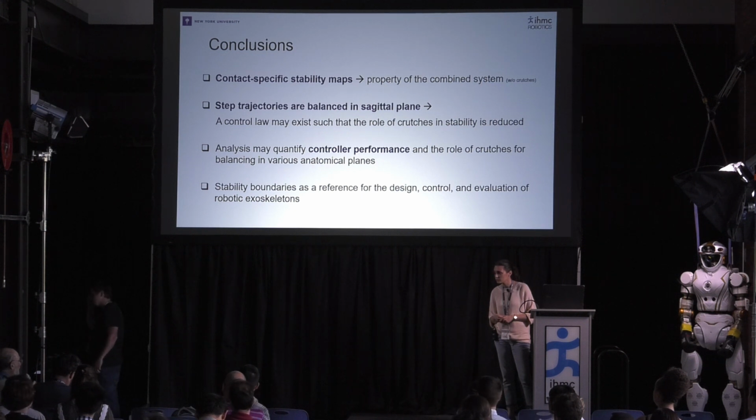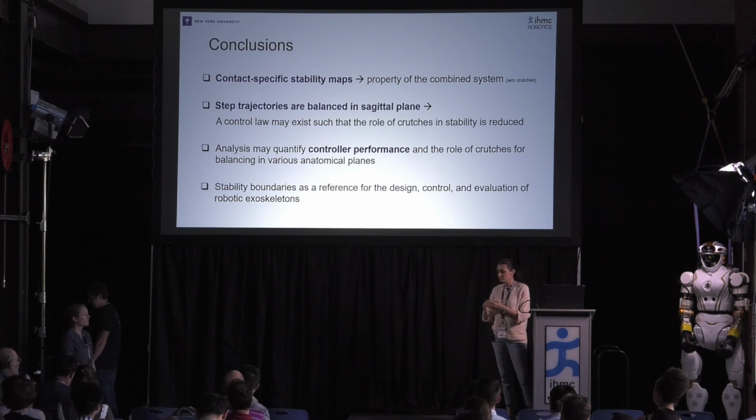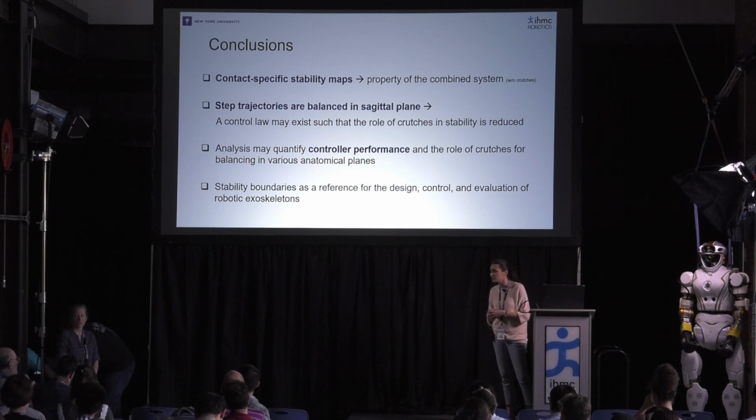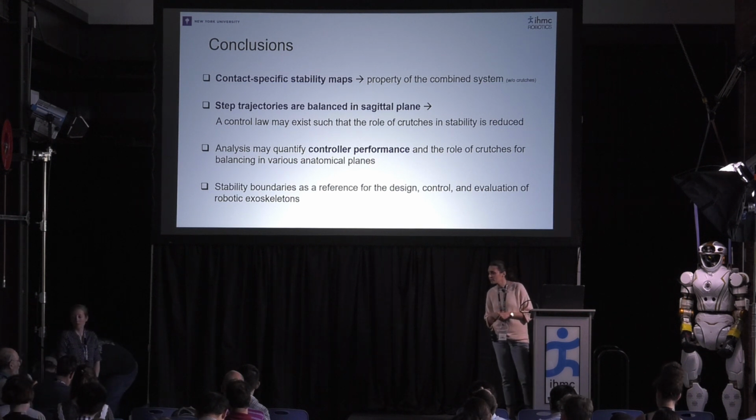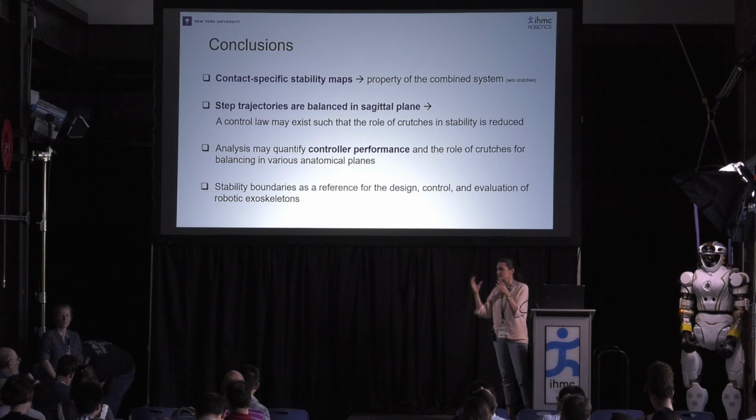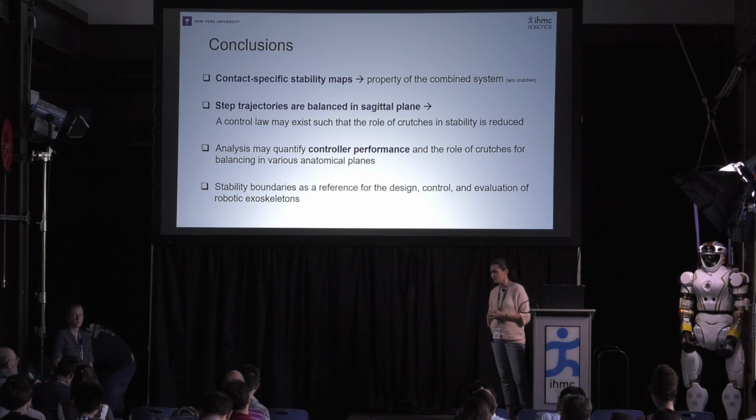But you're allowed to step to recover, or you're not allowed to step to recover. If you exit, we don't predict a good recovery strategy. We just predict that there has to be some kind of recovery outside of it. So the stability boundary is when it demands that you step. Yeah, it's similar to the set of points of non-return.